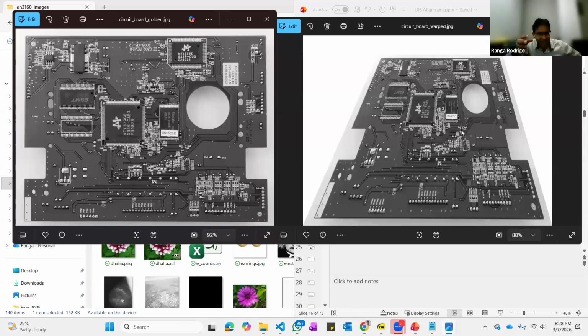There's a special name for that. In the machines, when they do circuit assembly, these kinds of things happen. Then you can see whether a diode has been rotated in the soldering. All these things you can detect. For that, we have to align the two images on top of each other. That's why you need to compute the homography automatically and align the image. But these things work only for plain images, not for 3D kinds of objects.